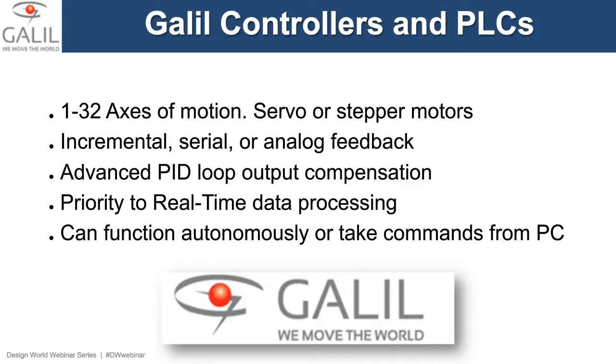That's feedback into the system that allows the controller to perform the deterministic task of maintaining those positions. Deterministic is really just running on a specific loop, a servo loop at exact intervals. That's really what's required to keep overall control of your system.